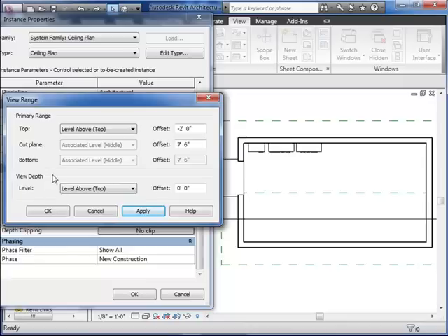In a ceiling we'd almost like to take this setting and flip it up here because it occurs here up above the top. Because I changed this to -2 but did not change this value, I left it at 0, I've actually created a view range up above the top of this floor plan, and therefore triggered the roof to display in my dashed green line beyond style. It's the same beyond style that we're using in the other floor plans, and again, if you wanted it to appear differently here in your ceiling plan, you would need to go to visibility graphics and modify it.